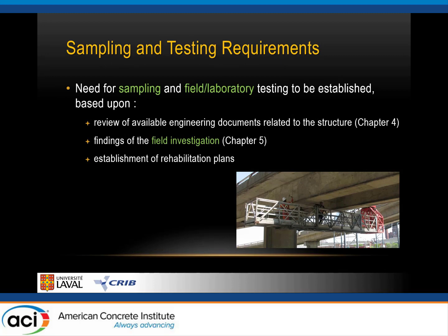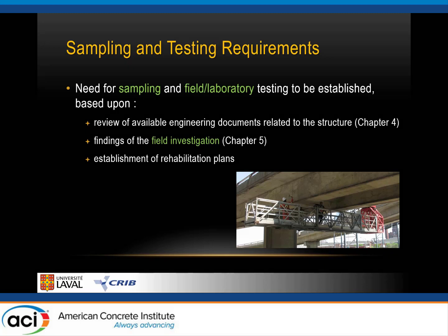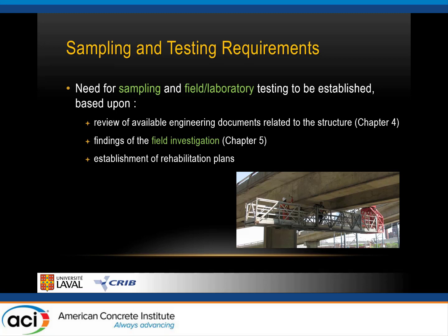First, before getting there, it is needed to evaluate why and to what extent we should sample and perform either field or laboratory testing. And this has to be preceded by a review of the actual information that we have of the structure.